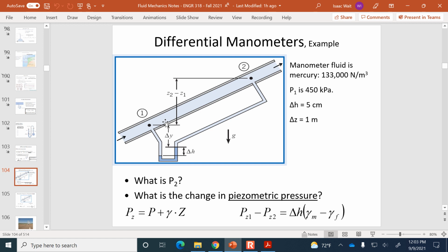But think about it. It would have been a little bit more confusing. What if location 2 was lower than location 1? Then it could have been that pressure was increasing because of the elevation difference, while simultaneously decreasing because of the pipe friction effect. So we don't always necessarily know downstream if it's a downhill pipe. You don't know if the pressure is going to be larger or smaller downhill, because it could be that the pressure is decreasing at a faster rate because there's lots of pipe friction. So sometimes you have to actually do the calculations before you know if the pressure downstream is higher or lower.